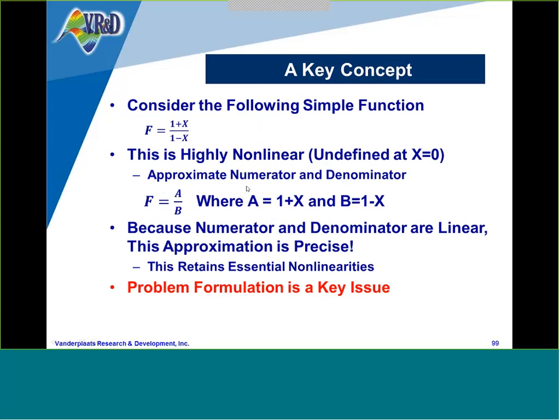The point being that if we look closely at our problem, very often simple changes in problem formulation yield very good results. And that's kind of a lecture all itself. I learned doing conceptual aircraft design that instead of letting wing loading be a design variable as designers usually do, if the wing area is a design variable, the optimization task becomes 10 times easier.